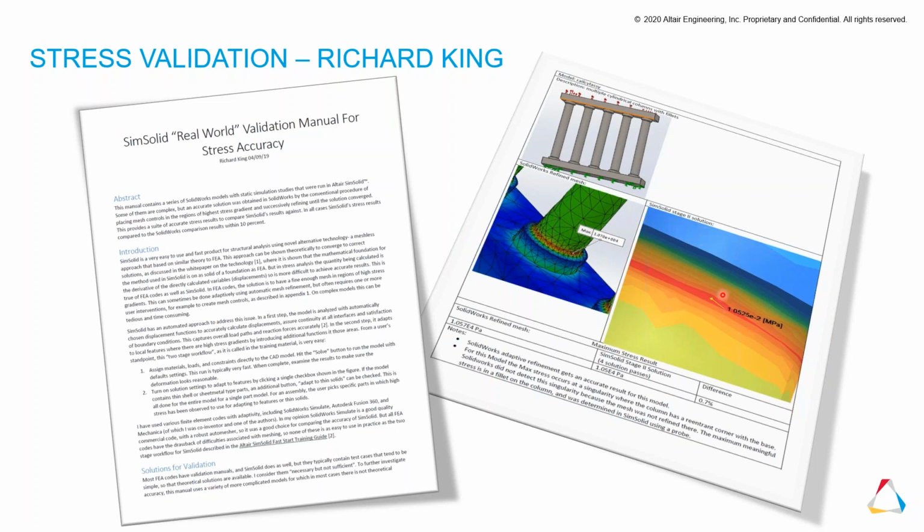SimSolid, how do we increase the accuracy? By just increasing the solution passes. Okay, so it's that simple to increase accuracy in SimSolid. So you can go through this handout as well. I've sent it to you guys. Look at the examples being compared, and you can see we actually have a very good agreement with the traditional finite element analysis here.